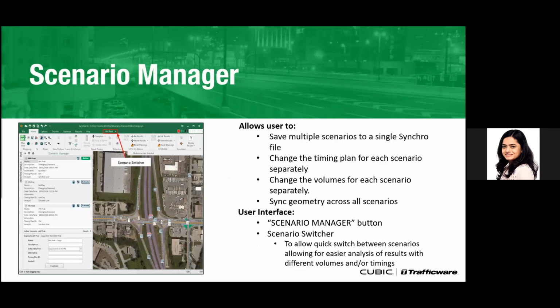Okay, so the next topic for today is Scenario Manager. Scenario Manager combines similar multiple scenarios into a single file format, which simplifies the electronic file management while also reducing the development time and maintenance. I would say one of the very significant benefits of Scenario Manager within Synchro 11 is the mitigation of coding errors that are very possible when you are managing multiple files and similar data, right?